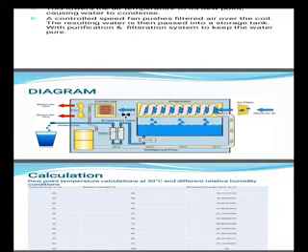The compressor is driven by a motor. So the compressor uses electricity as a source for compressing the refrigerant. It is then passed to the condenser. The vapor refrigerant is converted to liquid refrigerant in the condenser, wherein the temperature of the refrigerant decreases, but the pressure does not change. To decrease the pressure, we are using expansion valves. The expansion valve will bring the pressure back to its original value. It is then passed again to the evaporator.